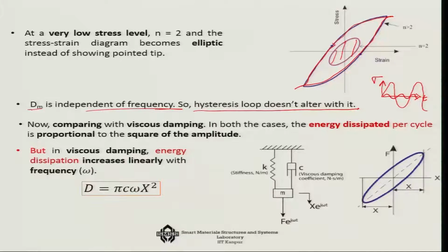Why I am telling this is that in case of a viscoelastic material or a damping, a rubber damping etc., the excitation frequency matters a lot. So, suppose for this stress level, even if it is a relatively high frequency or a relatively low frequency, in all the cases there will be no change in this energy dissipation, as long as the amplitude remains constant. Whereas, for viscoelastic material there will be a tremendous change between low frequency and high frequency.